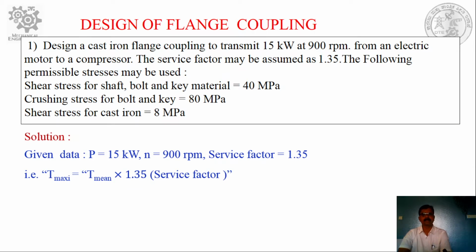Here he has given the service factor 1.35. You multiply what we obtained from that equation by the service factor, and we get the maximum torque